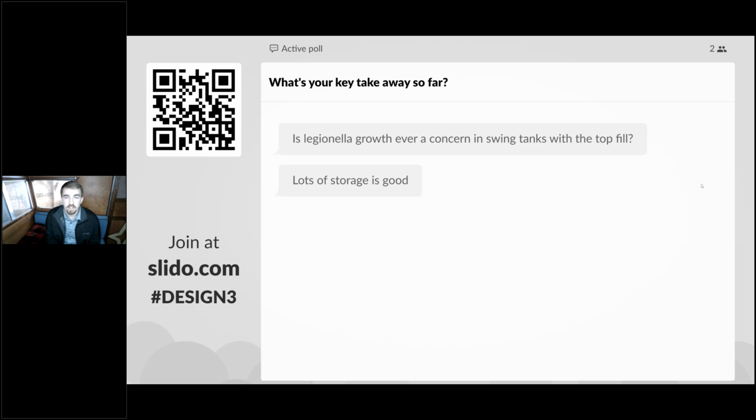But in terms of the top fill, I'm not totally sure if I'm interpreting what you're asking correctly, but the top fill of how we were talking about the storage connections between the heat pump and storage is a little bit different than the swing tank setup, because the swing tank, we're aiming to mix all this water up and provide a more consistent temperature as the hot water from the primary storage fills into that and essentially heats it up as it mixes in.